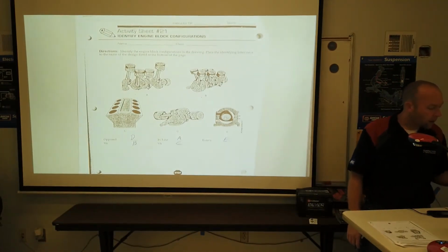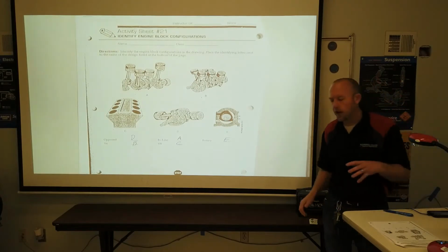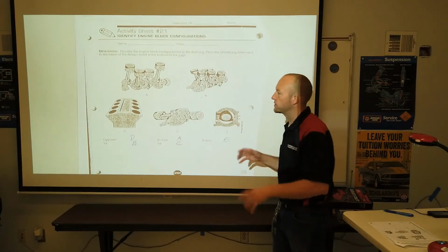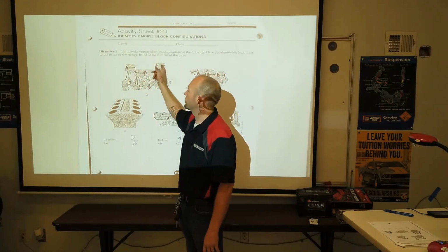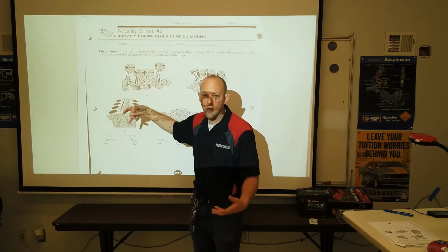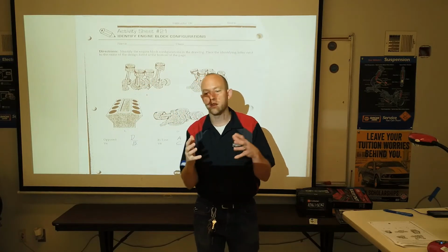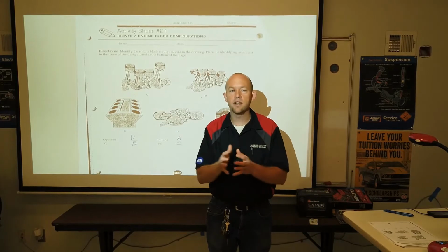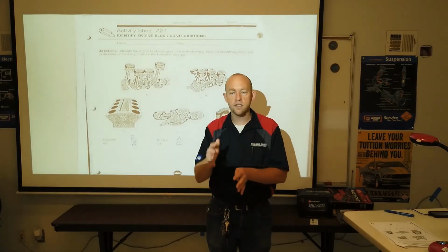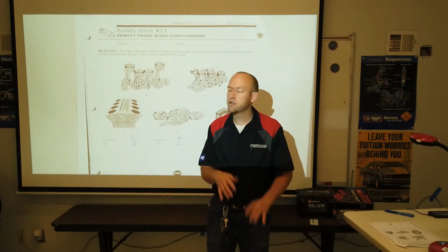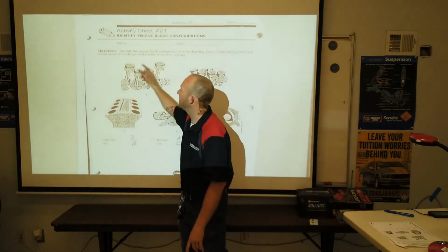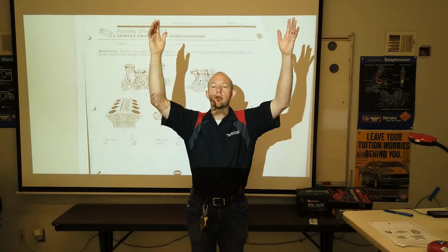A couple of things that I want to point out while we're here on this picture. You'll notice, and we've had the conversation about companion cylinders, that there's 2 pistons that are up and 2 pistons that are down in this picture, and that's typical with any even numbered cylinder motor. So anytime you have 4, 6, 8, 10, 12 cylinder motors, they're going to design them to have companion cylinders because of balance. So as those 2 pistons go up, then the other 2 pistons are going down.